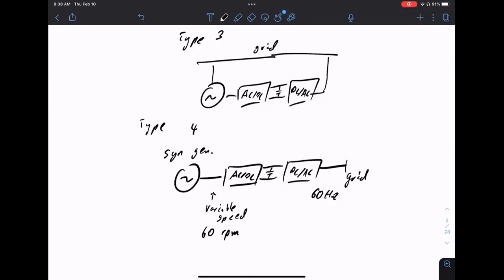Of course, it took a while to get to this point, because you have to wait until you can pass, let's say, 5 megawatts of power through these two stages. These are not small converters. If this is a 5 megawatt turbine, you have to have 5 megawatts go through this converter, this capacitor, this converter, and out to the grid. All of these are expensive components, but the main benefit, again, is that there's no gearbox. You get rid of the gearbox.